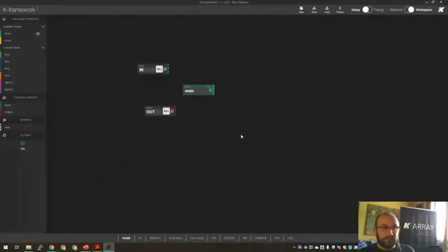So I need the groups to do a Q, to do serious tuning on the amplifier. So if I leave it with something on board, then when I bring it back on the workspace, everything is there, obviously. In this case, I have a group for the inputs. In inputs, we have a volume and 3 parametric filters, each channel. So here I have an amplifier that has 4 channels, so I can decide to group whatever I want. So in this case, I have input groups on 1 and 2, and then I have the output group to 1, 2, and 3. This is usually a 2.1 configuration, so stereo tops and mono subs.